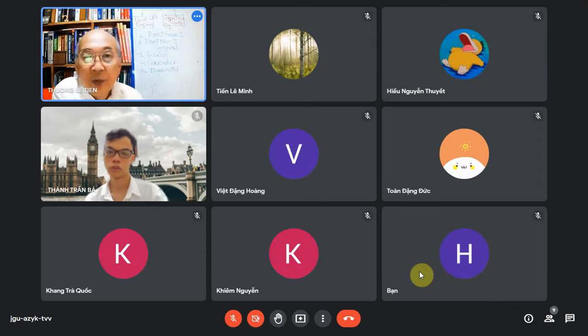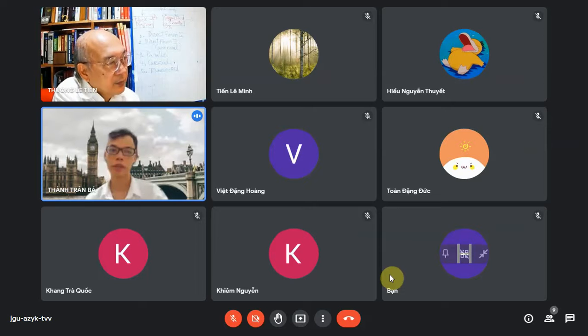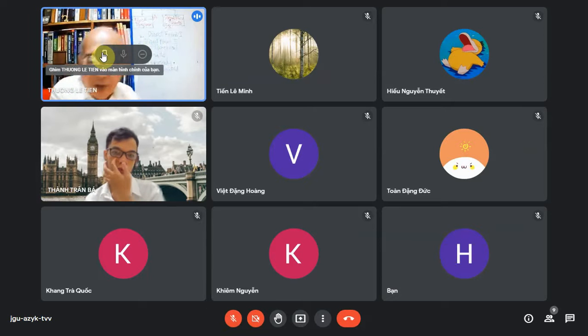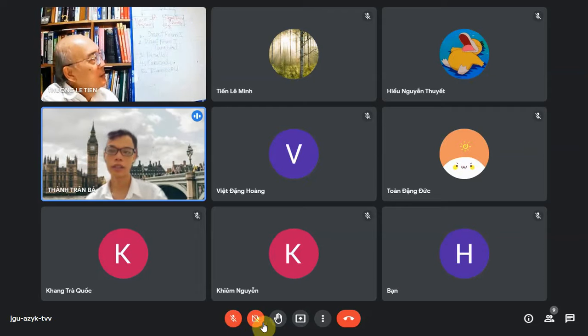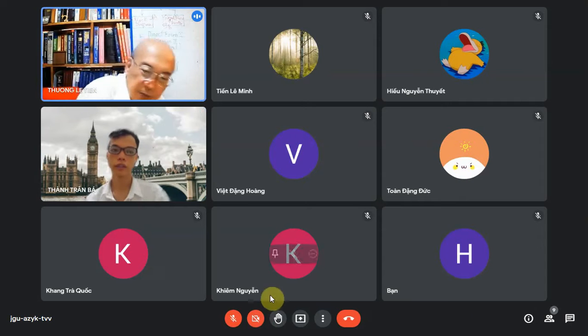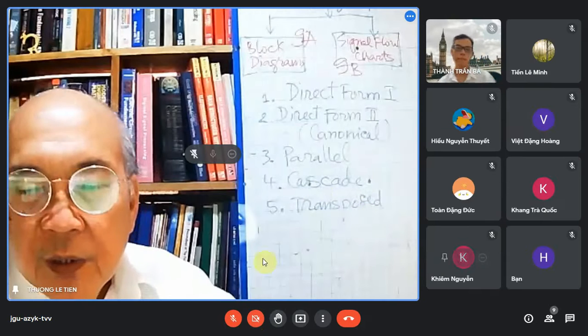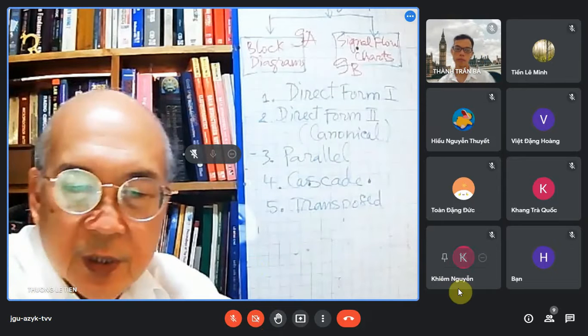Han, can you say again what the FIR and IIR systems are? Just provide the keynote. FIR has a finite number of samples, a finite number of filter coefficients. And IIR has an infinite number of filter coefficients, or an infinite number of samples of the impulse response. Okay.